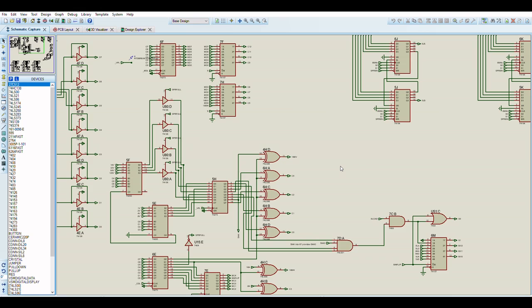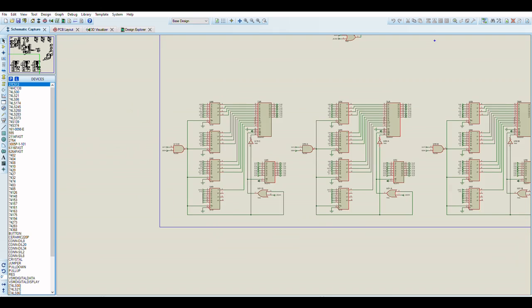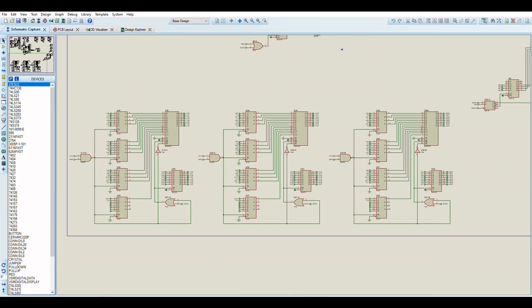Whether or not a sprite is horizontally or vertically flipped is again just a simple case of deciding on which signals to invert and when, because the vertical position of the sprite is then used to directly address into what is really interesting, the 3-bit plane sprite data lookup.